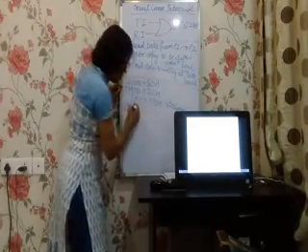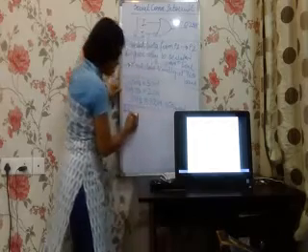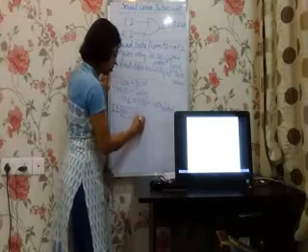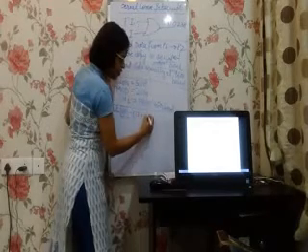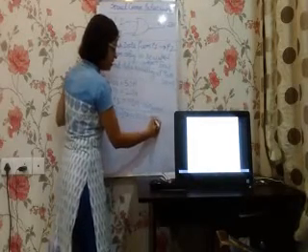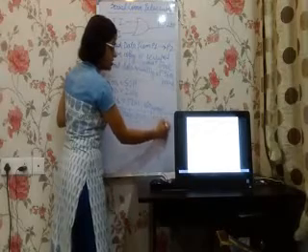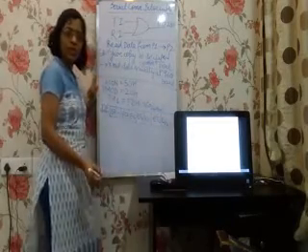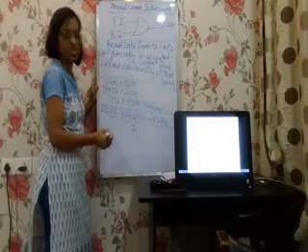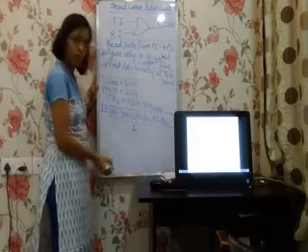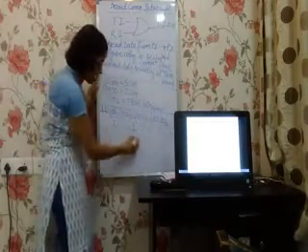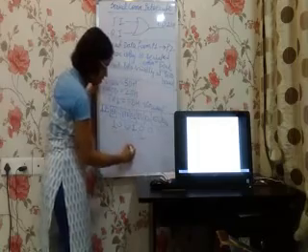Let me draw the format of IE once again over here. We have EA, enable all, ET2, not used, ES, this is our bit of interest, ET1, EX1, ET0 and EX0. Which bit do we want to configure? It's the serial communication interrupt, so we have to make ES 1. Enable all also has to be made 1. The rest of the bits will be 0. So you have to load IE with the value 90H.